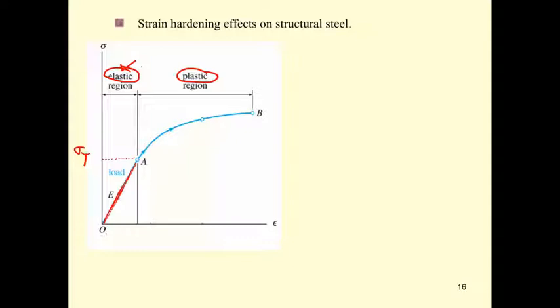But for example, if you have steel 1 meter and you pull it past this elastic region and go to the plastic region. If you pull it a small amount and get 1.02 meter, that's in the elastic behavior, right? But if you pull it to 1.10 meter, it's going to come to the plastic region. And when you release the force, it won't go back down here. It will come back following its original linear behavior like this.